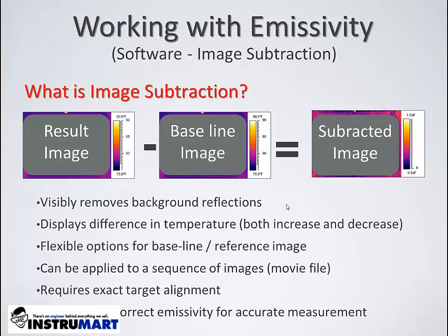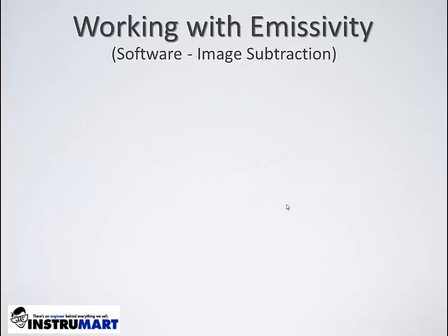A final point regarding image subtraction. If the objective is to conduct quantitative analysis of the subtracted imagery, the correct target emissivity values must still be applied. If we were to review the math behind image subtraction, it would show emissivity does not cancel out. Okay, let me show you an example of image subtraction and how it works.